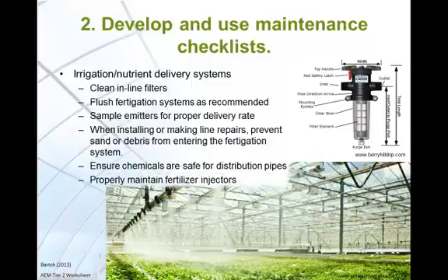Lastly, maintain fertilizer injectors. Getting the right concentration is dependent on a properly functioning injector. Know your injector type, Venturi, positive displacement, or membrane type, and perform maintenance as required. For Venturi type, it is essential to maintain pressure and keep the injector clean. Positive displacement is the most accurate and reliable, but make sure that the system is injecting the correct volume. Over time, the membrane in a membrane type can lose flexibility.